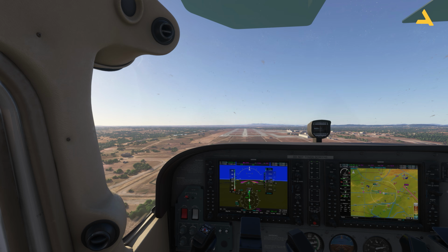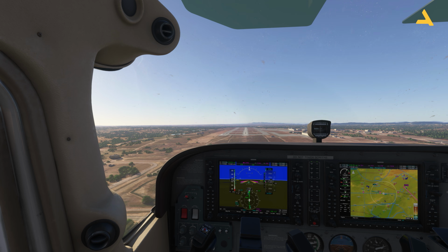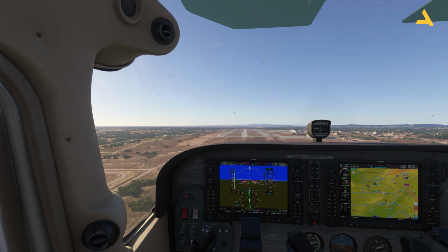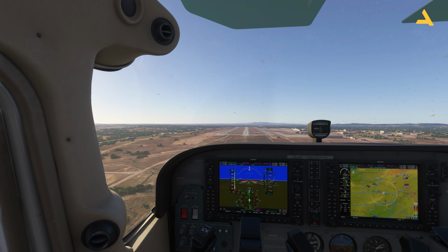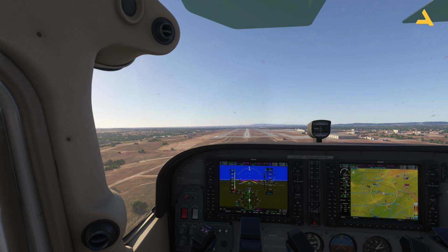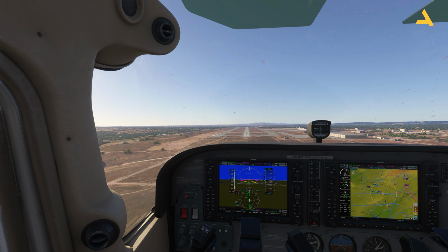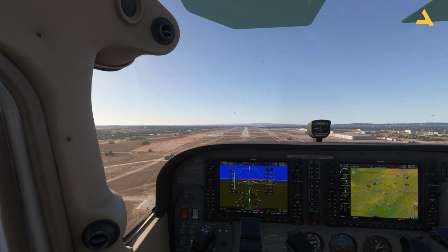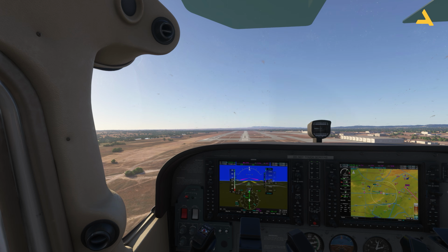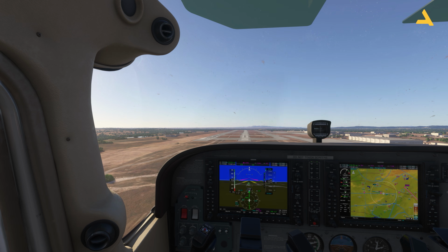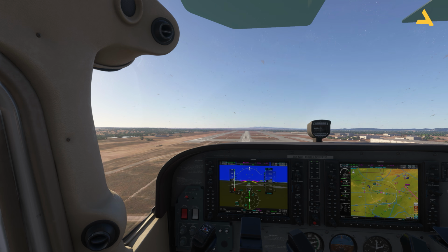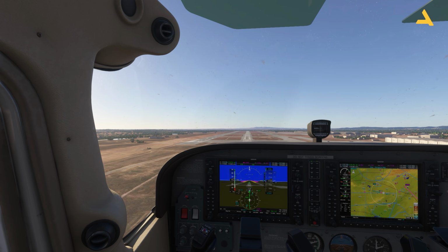So I hope this was a useful video, and now you can do the VOR navigation, and you can land the plane on ILS. Even with the VOR approach, you can visually land the plane. So initially, if you're really new to the VOR navigation, the things will get a bit confusing, but just try making some flight plans. Try flying different routes and different airports, and see if you can just find your way through the airspace. Remember this thing, don't look at the map.